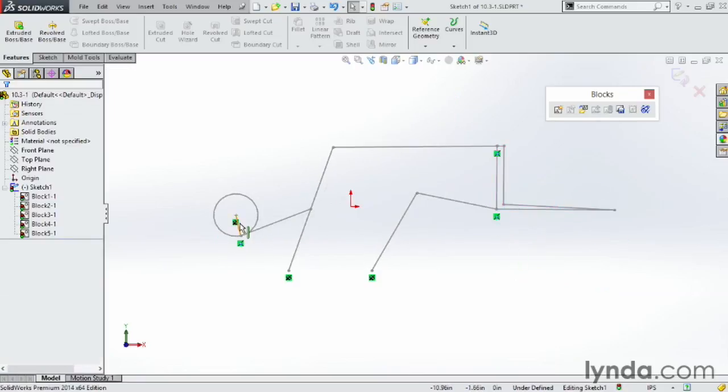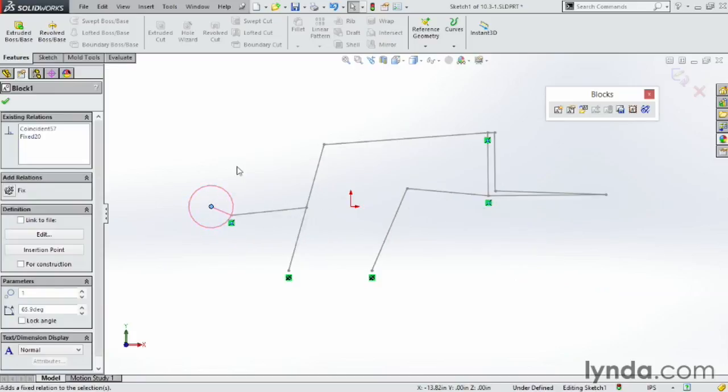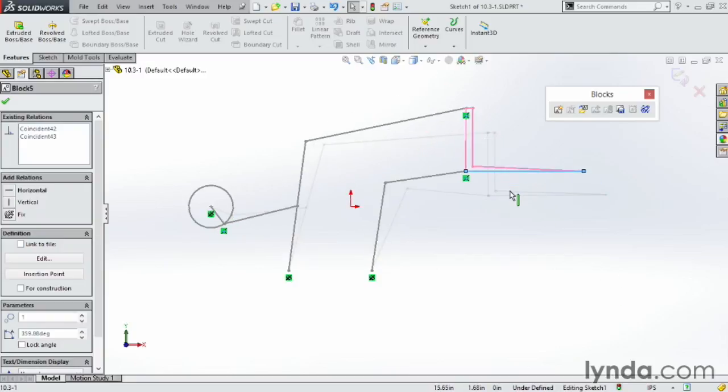And maybe that's not the right location, so go ahead and click on that, hit delete. Maybe we want to drag that back just a little bit. In this case here, we'll say make fixed. And then we can see what happens as this goes up and as it goes down. You might have to play around with it a little bit to refine the mechanism further. But the point is you can make individual units, combine them together as a block, and then we can actually simulate them in the computer as a sketch way before we actually create any individual components.